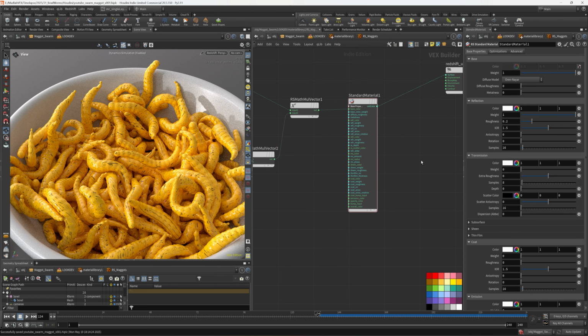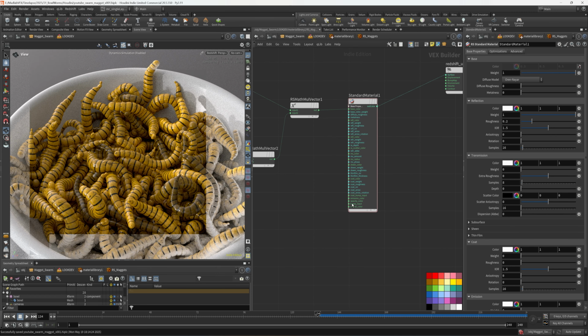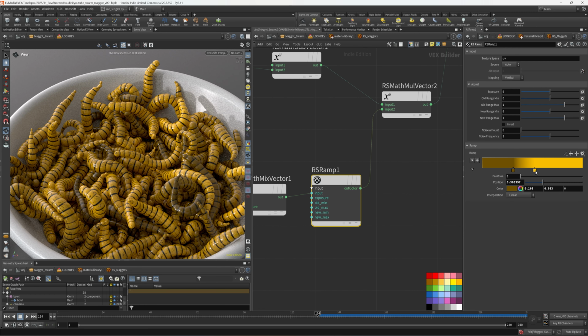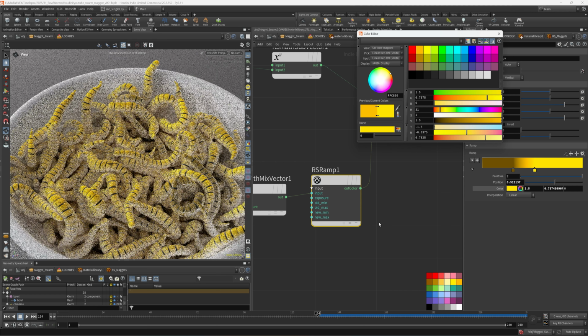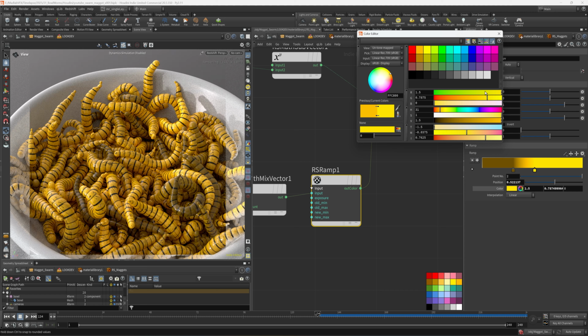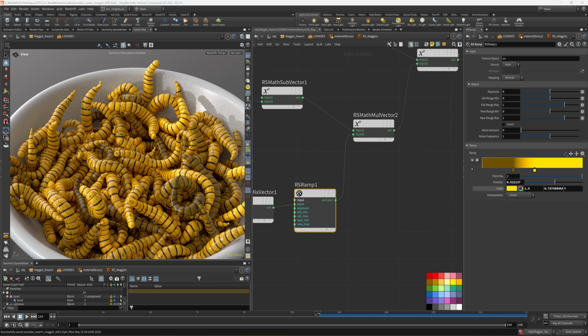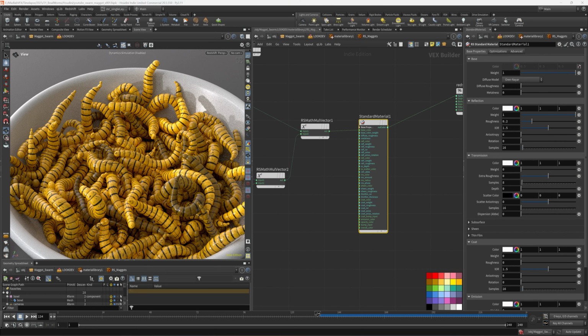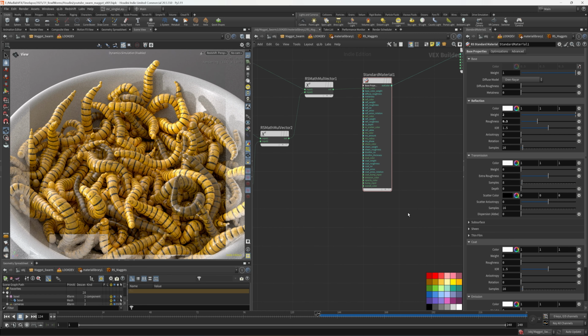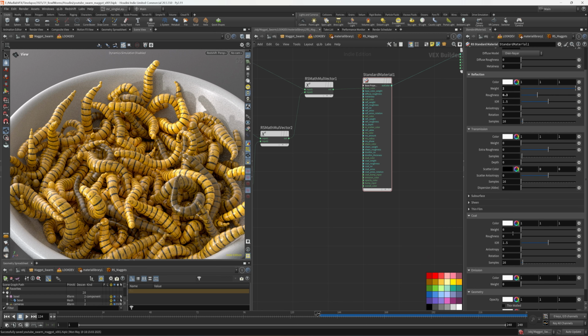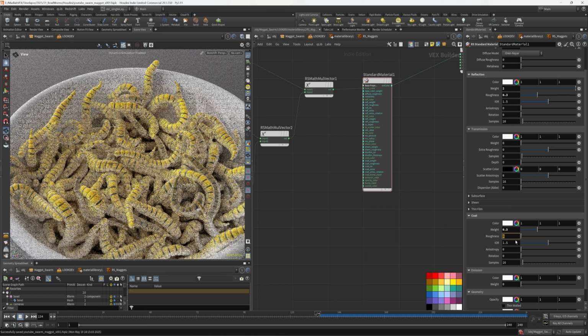Let's see the visuals. The visuals look interesting. In the ramp here, let's increase the value for this color like 1.5 to create more brighter worms. Let's change some attributes here in the shader, like roughness should be around 0.3. Increase the weight of the roughness to 2. Enable the coat here, a second pass of reflection around 0.3 in the weight, in the roughness 0.1.